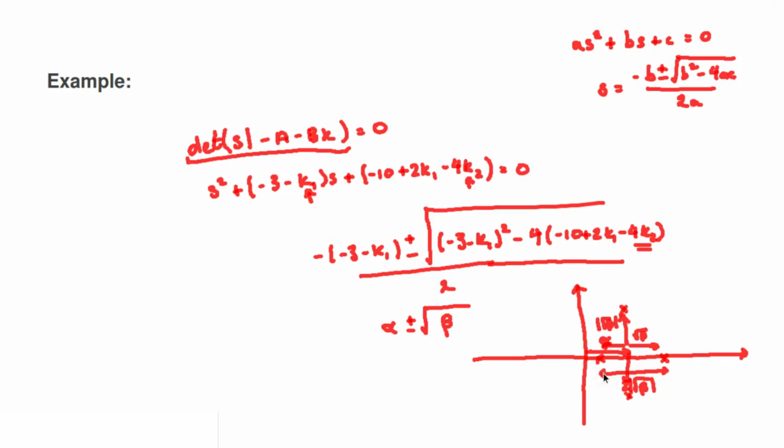So we can also make the distance between the real poles, or the distance between the complex poles, whatever we like too. So in fact, the answer to our question is we can achieve almost any possible set of pole locations. The only constraint is that if we have complex poles, they come in a complex conjugate pair. And actually, this is a general fact. Whenever the system is controllable, so whenever the pair of matrices A, B is controllable, we can freely assign the closed-loop poles to be wherever we want in the complex plane, provided that if we have one with a certain imaginary part, we have its corresponding conjugate pole as well.